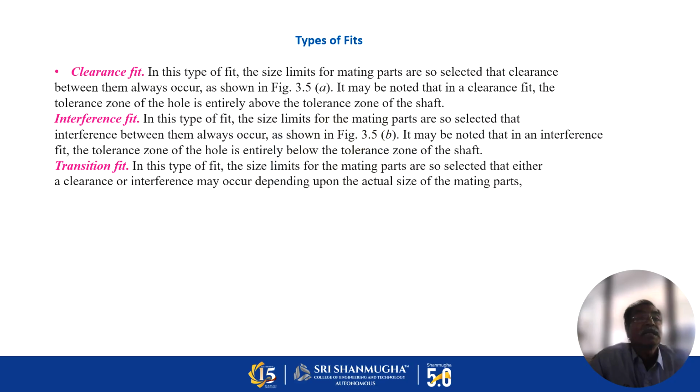Next is called the transition fit. In this type of fit, the size limits for the mating parts are so selected that either a clearance or interference may occur depending upon the actual size of the mating parts. In the transition fit, tolerance zones of the hole and shaft overlap. The transition fit may be force fit, tight fit, or push fit.